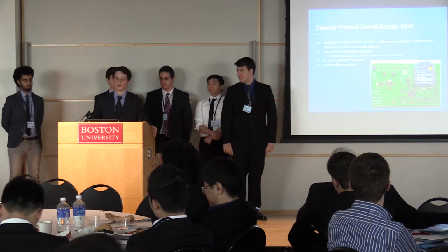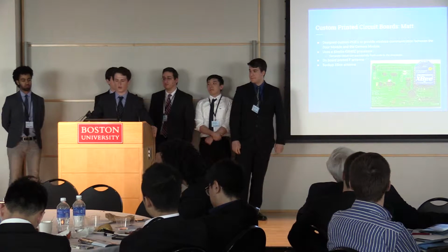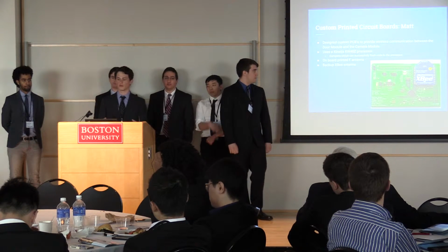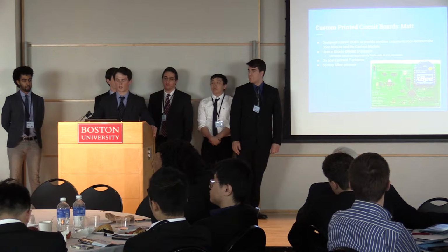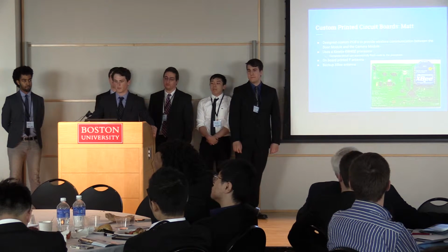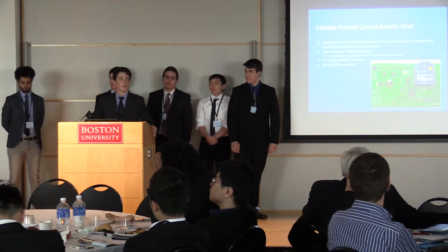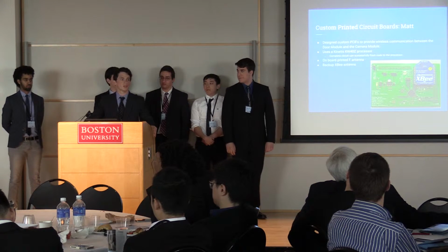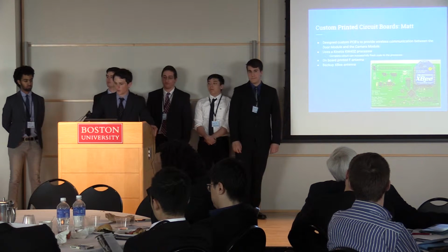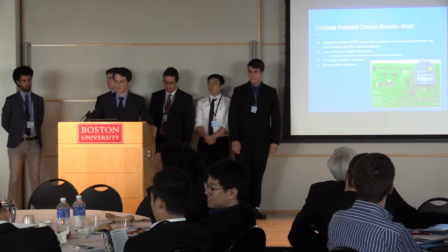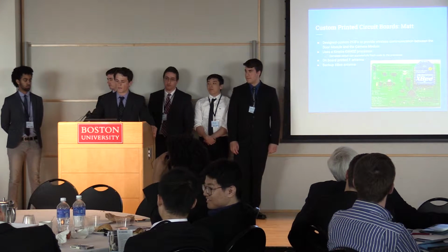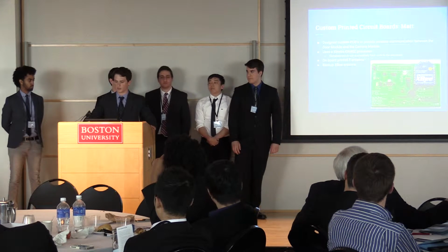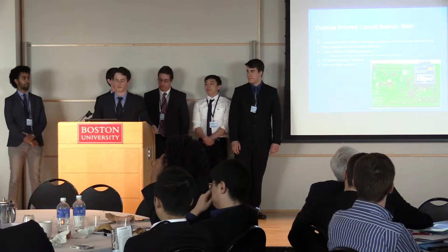I was responsible for the design of the custom printed circuit boards, from the schematics and actually taking the critical parts of the development boards and integrating them so they could interface as both a camera module PCB and a door module PCB. I also laid out the part placements and the traces and did the final assembly of the printed circuit boards. It includes the Kinetis chip, which is flashable so we can actually get code onto it, and also the RF antenna design from the dev board, which currently has some impedance issues, but overall the hardware works fine.